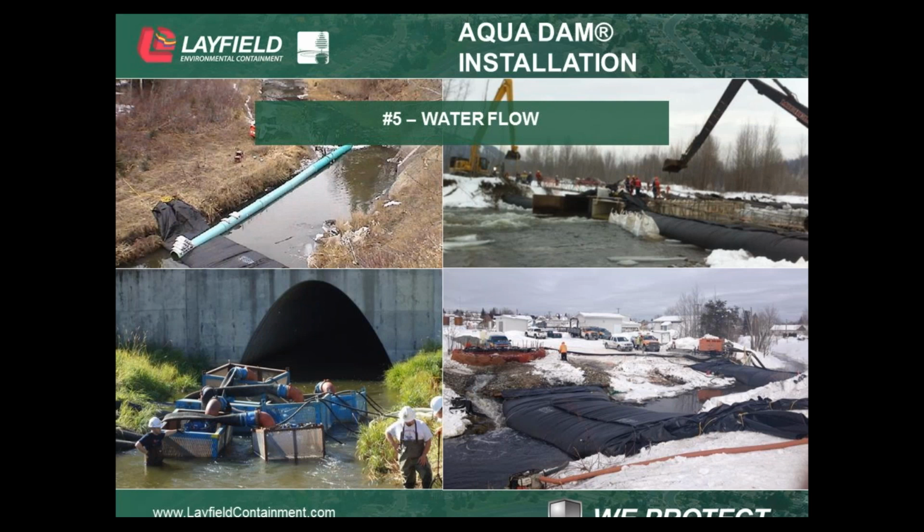There's different methods depending upon the type of flow, depending on the size of the stream, different ways we can do the pipe work. Top right, we've got a couple of superflumes in place with a front wing wall diverting flow into the superflume. We've got aqua dams running out to it in upstream and downstream scenario, and we've got two excavators working on either side doing their work.